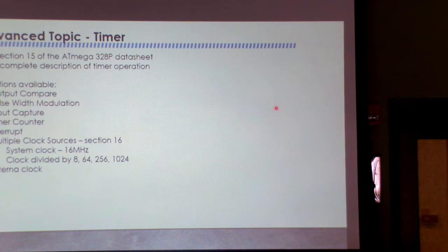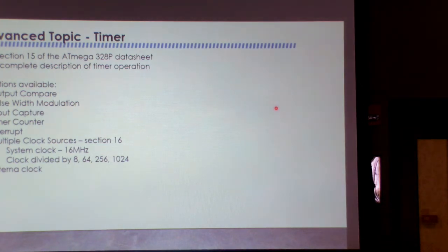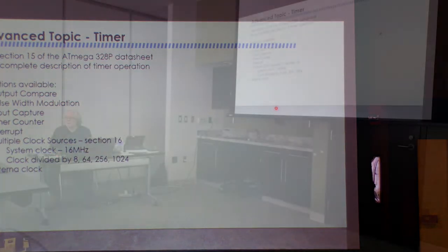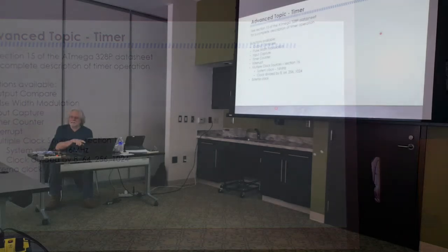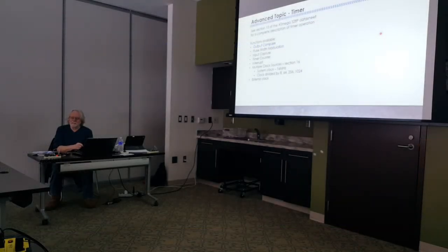And then there's an external clock source, which means you have to have some kind of clock source to drive the pin on the processor with. So you might have a very stable 1 megahertz clock. It might be temperature compensated and tuned to WWV and all that. And so now you've got a 1 megahertz clock that's 1.000000 megahertz. And now you can have a very stable clock, no matter what the 16 megahertz clock is doing. If the 1 megahertz clock is stable, your timer for your 24-hour clock would be stable.